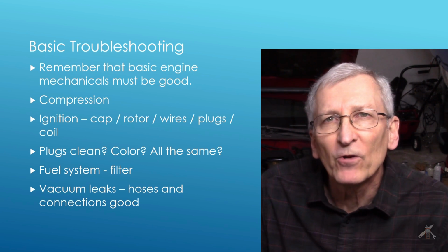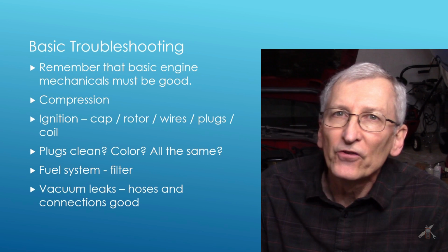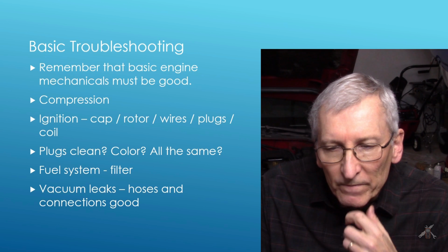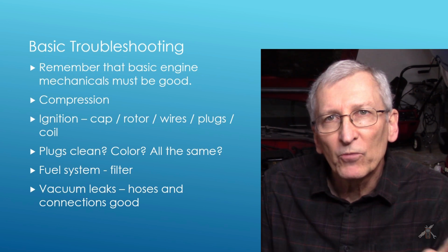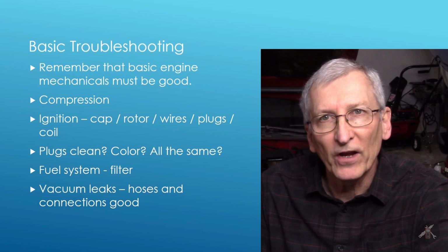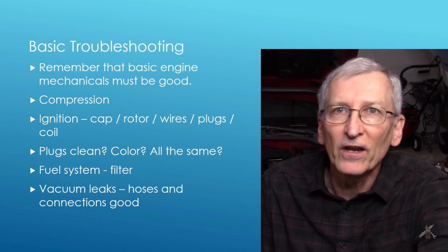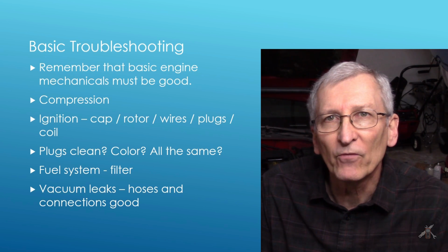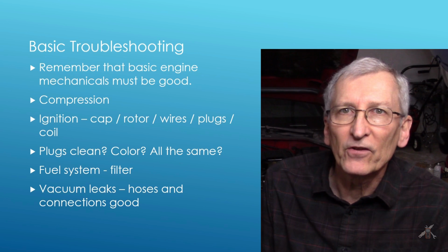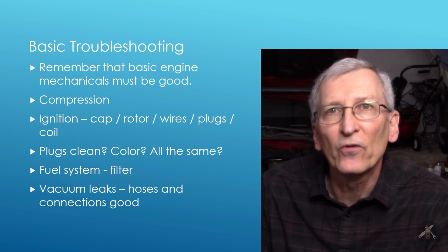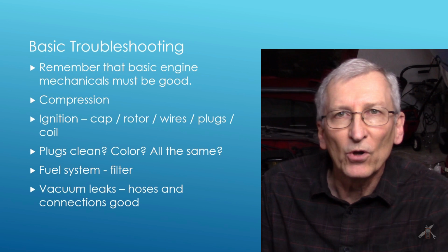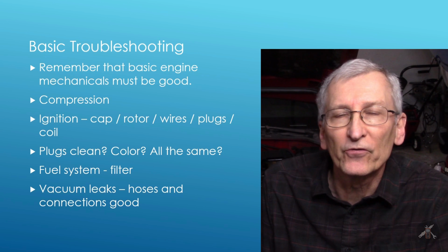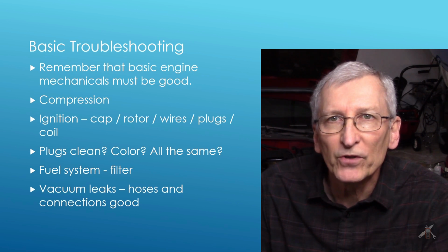On ignition, I'll just add one in here that I don't have on the chart. Distributor. Somebody asked me, hey, should I replace the distributor? If your cap, rotor, wires, and your ignition module inside the distributor on these high energy ignitions are bad, what's in that distributor and what'd you replace? I've got a video from way back when I put the engine in this car, several years ago. I rebuilt the whole thing, pulled it out, replaced the pickup, I did everything and kept the original distributor. It takes a little bit more work, but you can do it.